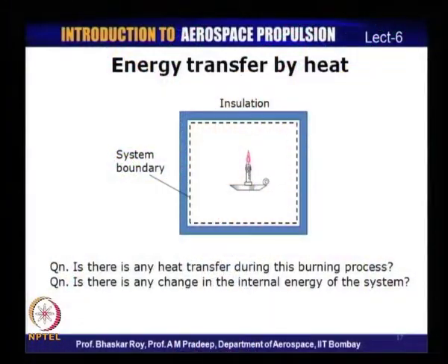So, we have here a candle which is burning within a system volume, and the system is insulated. Because the system is insulated, there is no energy interaction possible between the system and the surroundings, and therefore, obviously, there cannot be any heat transfer between the system and surroundings. So, thermodynamically, there is no heat transfer taking place in this process. And the second question was, is there any change in internal energy? Well, you may wonder that because the candle is burning, there should be a change in internal energy of the system. Well, the answer to that question is that there is no change in internal energy as well.